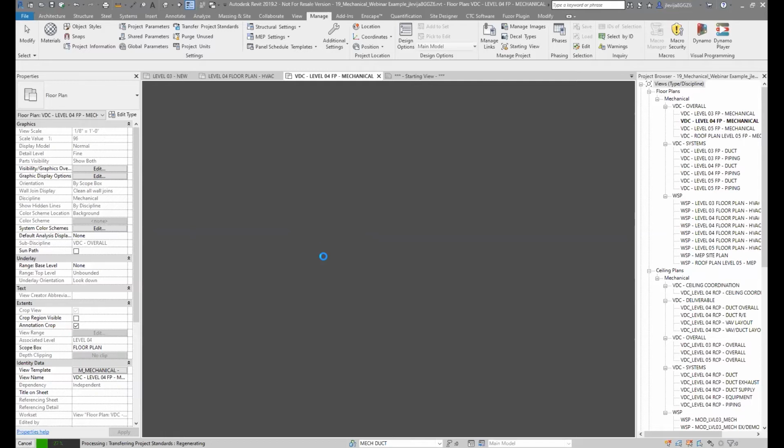So those are some of those general items there. Also, you'll bring across your starter view, and then you'll want to get that applied. On top of bringing the starter view, which is right here in the Manage tab, after bringing that across, what you'll also want to bring across is whatever title block your company is utilizing at that point.